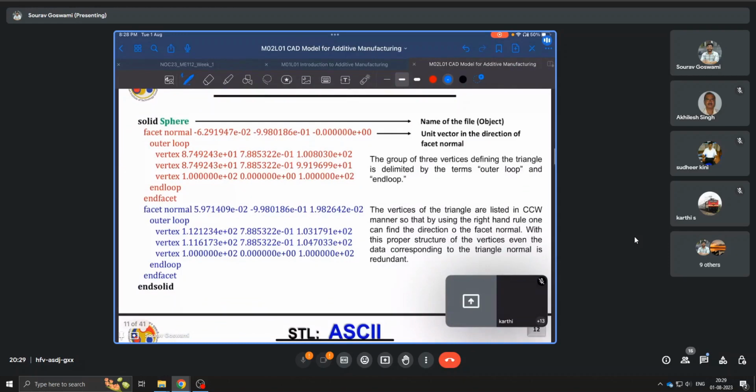Up here, an example of an STL file. So as we said, it describes facets. The first line will contain information about the outward normal. It's important. So any surface has two normals, one going inward, one outward. This always describes the outward normal. When I say outward, along the direction of the normal, we will have empty space. When I go against the normal, I expect to find something. Maybe I'm going inside whatever surface this was.